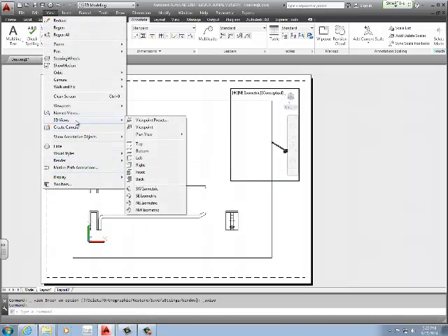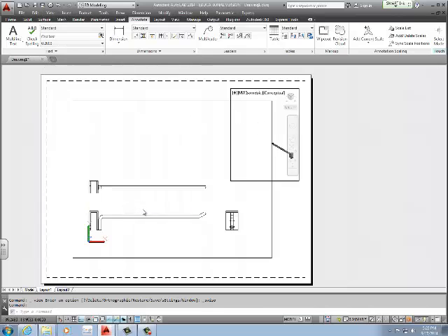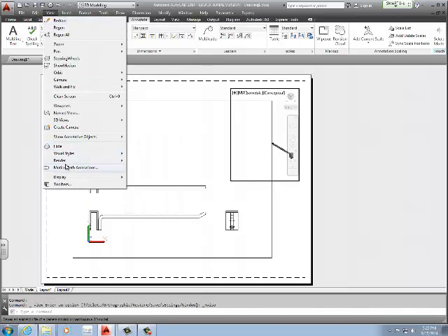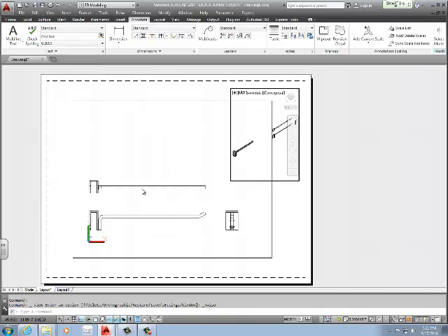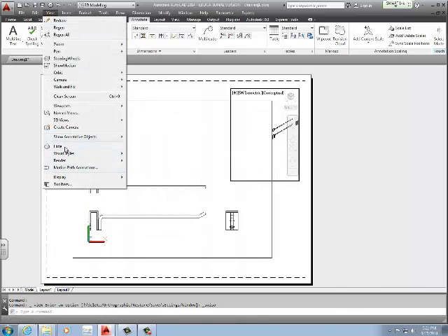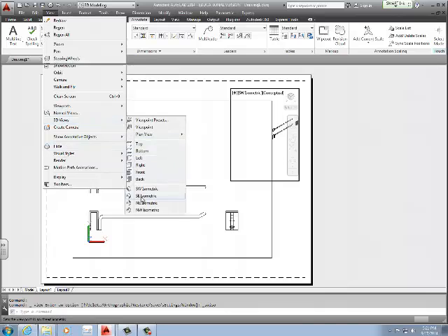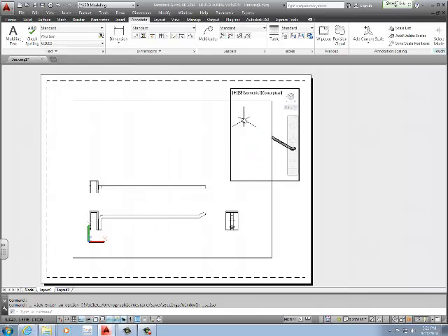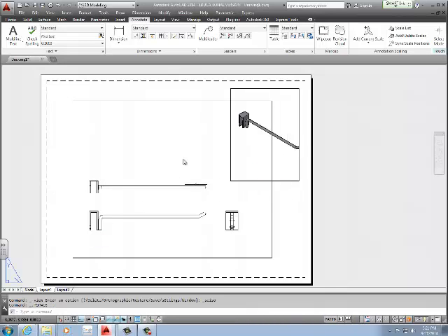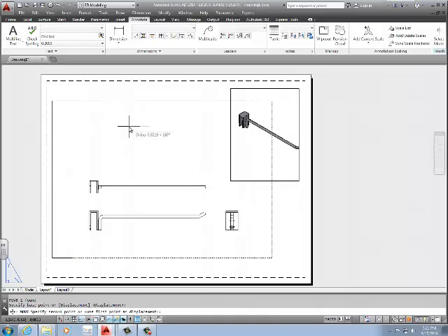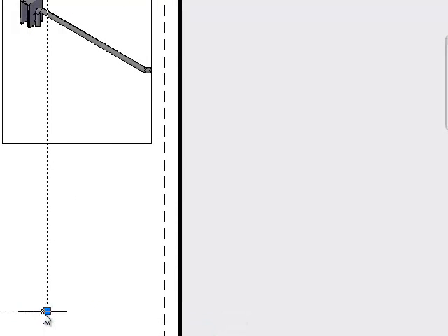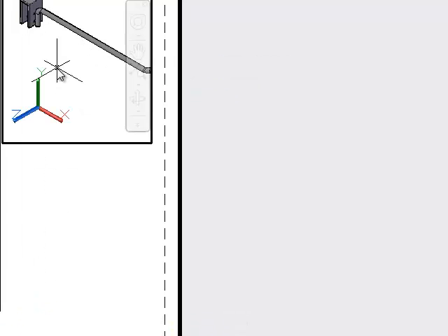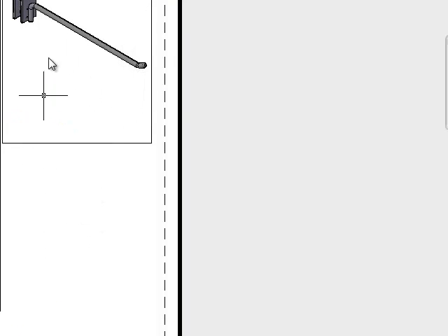Let's do this northwest. No, this is tricky trying to figure out which exact 3D view to go with. So that's going to be my path. The only thing I have to add to that is a fillet, because you'll never get a 90-degree turn on a wire. So what we're going to do is a fillet. We're going to type in the radius. Most machines will take you with the radius.